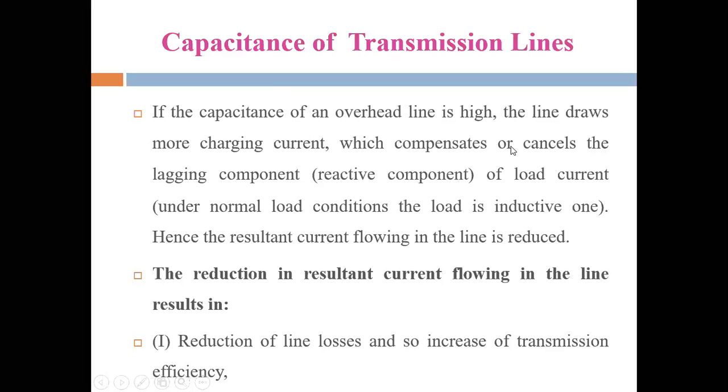This cancels the lagging reactive component under normal load conditions, hence the resultant current flowing in the line is reduced. The reduction in current reduces the line losses and so increases the transmission efficiency.